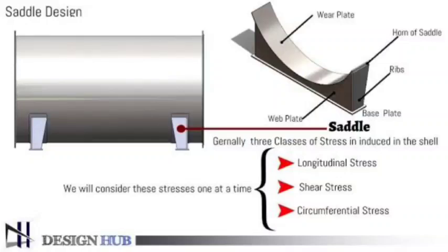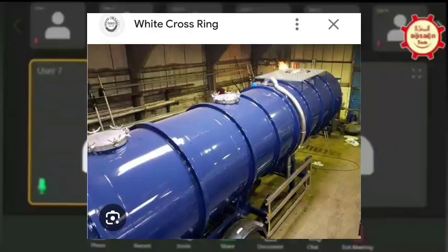And even if that is also not passing, then the last option, which is not recommended, is to add the stiffening saddle ring. But whenever you use the first and second option, there are 99.9% chances that your saddle will pass. Yeah, so we have to conclude that. Okay, Abhishek, you got your answer.